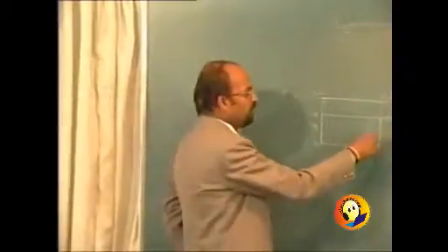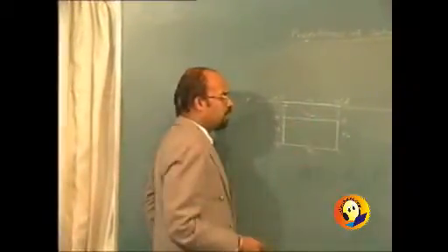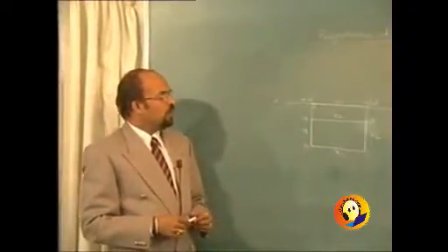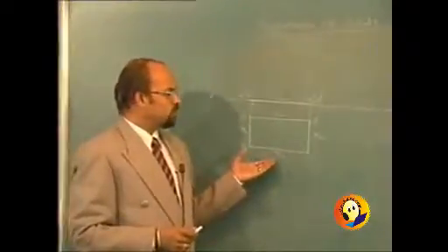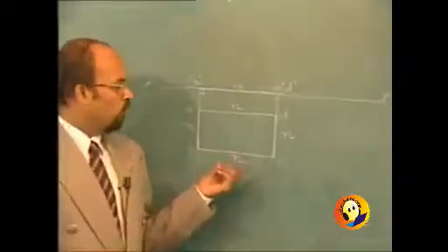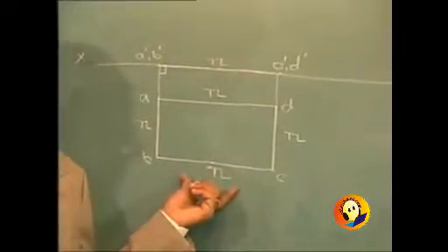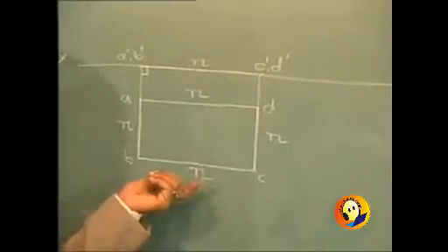And if we continue in this form, then we find that all the lines are seen in true length in the plan, and the corresponding front view is on XY. Now this is in relation to the projections of lines only. When we go for the true shape of the plane in horizontal plane, or rather in plan or in elevation, obviously we are talking about the projections of lines.